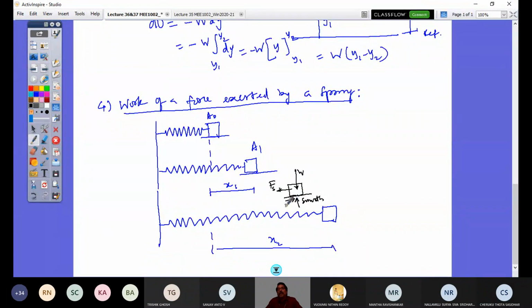And that friction force, Fk, right? So now, if it is a smooth surface, this Fk is 0. The smooth surface, so Fk is 0. So this is not there. Only you would have your vertical reaction R. And W and R balance, and they are at right angles to the expected displacement. So these too will not participate in the work done equation, as we have seen just some time back.